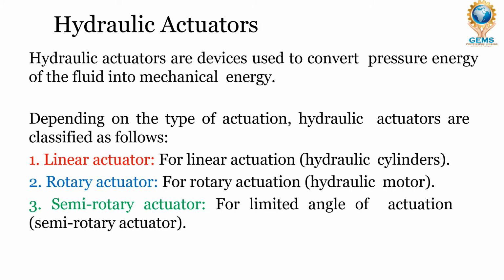So hydraulic actuators. What are hydraulic actuators? Hydraulic actuators are devices used to convert pressure energy of the fluid into mechanical energy. Depending on the type of actuation, hydraulic actuators are classified as follows. Linear actuator for linear actuation, hydraulic cylinders, and rotary actuator for rotary actuation like hydraulic motors. Semi-rotary actuator for limited angle of actuation.